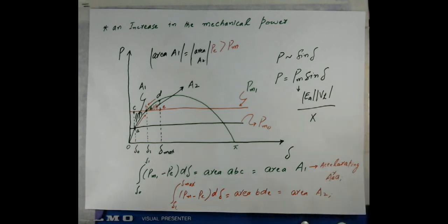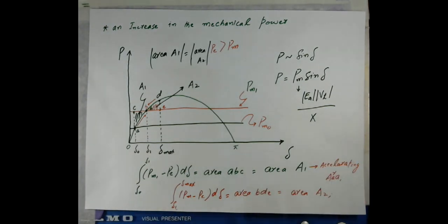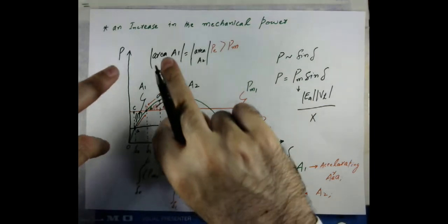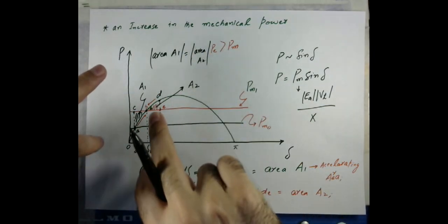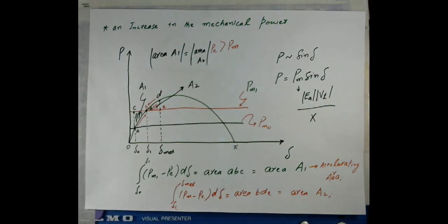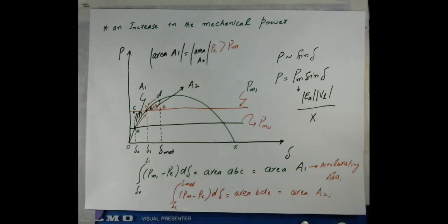And as I discussed at the beginning, this method is basically based on the graphical representation of the energy rather than solving the swing equation. So if the two areas are equal during acceleration and deceleration, then the stable operation is ensured. So now we have discussed this criteria even with the help of this example. So let me now quickly summarize the content.